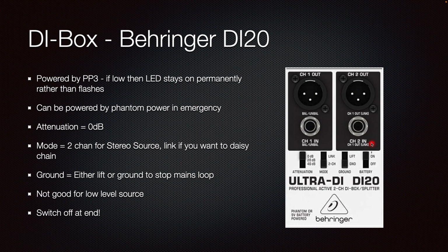So if it goes permanent, swap this out. We keep a few spares up at the desk and put a new battery in it a bit later. You can actually power this on phantom power in an emergency. I wouldn't recommend it, but you can do. Set the attenuation at 0. The only time you'd ever move that is if, for some reason, you were taking a speaker output into it and needing to push that down.